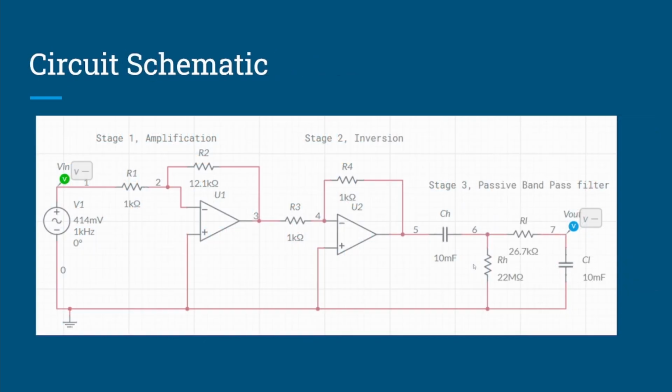So looking at our circuit design, this is just going to be a quick overview. Essentially, after accepting the voltage from the biosignal, in this case sweat, we amplify the signal via an inverting operational amplifier. In order to actually use this amplified signal, however, we must return it to a usable form, and that's where stage 2 comes into play, with the inverting operational amplifier being used again.